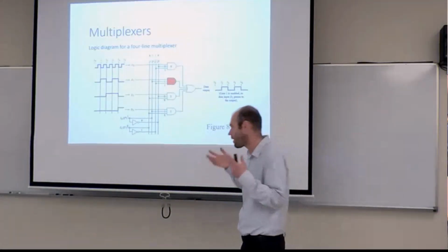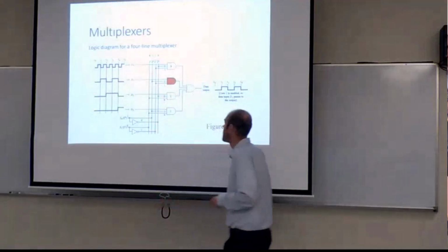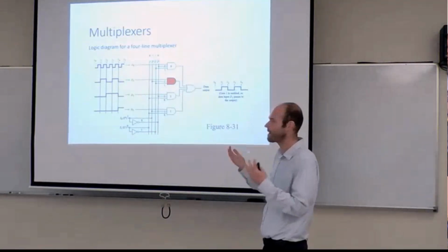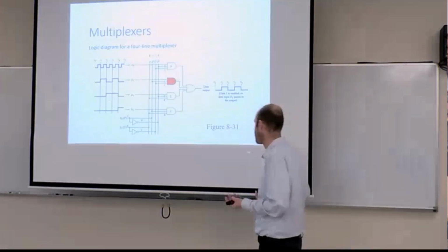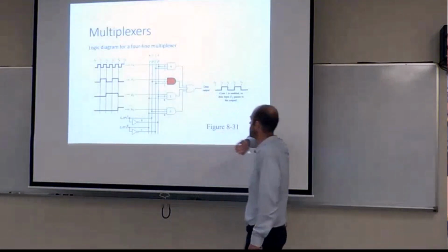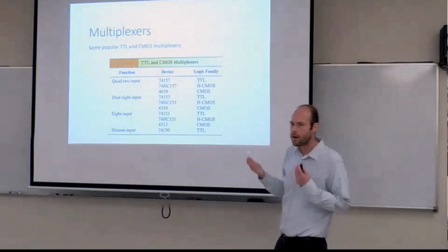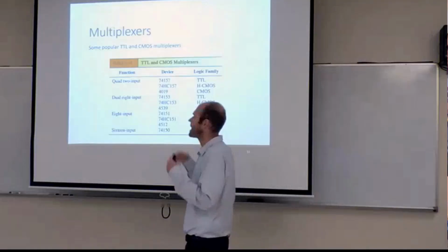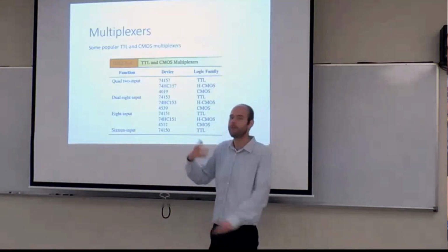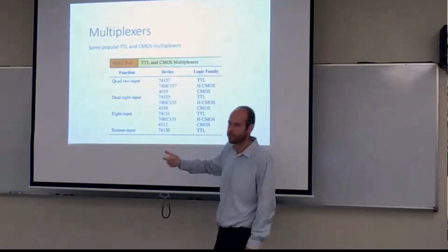Internally, we don't need to build our own multiplexer, but it is made up of all our basic logic gates. And just by basically using AND as an enable functionality, you can let only one data channel go through to your output. And there are a lot of different hardware pieces of this. If you don't want to buy an entire microcontroller, you just need a multiplexing functionality, which is far more common than a lot of other things. You just need a multiplexer.